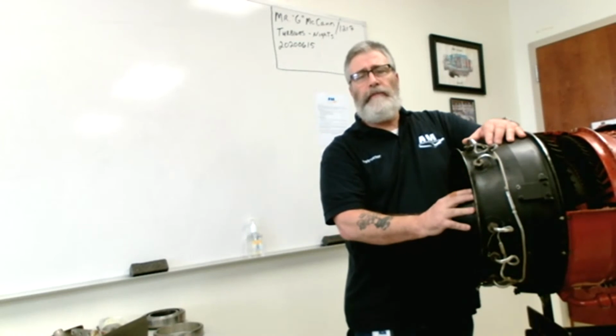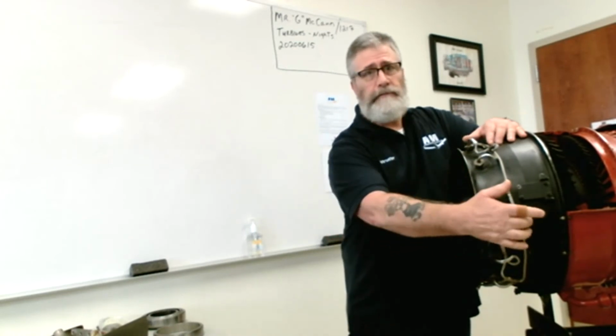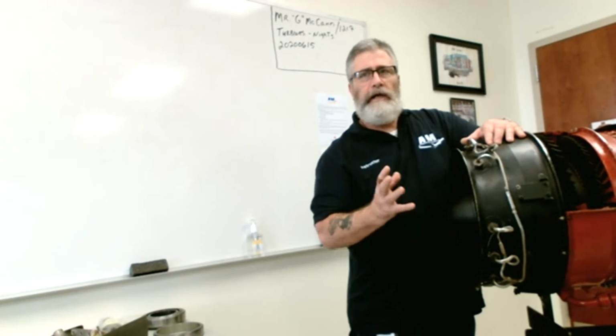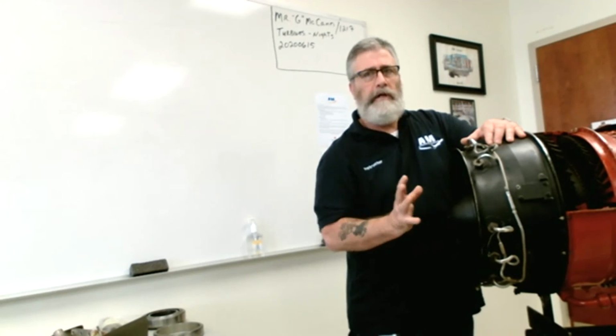The parts that are involved are a fuel source, which is either fuel nozzles or sometimes called a fuel rail. The other thing it needs is a source of ignition. Then there's a thing that goes up inside, which it's better to show you than to talk about, called a flame holder. It's just a big piece of thick metal that goes about halfway up, and that just sets up a little back pressure, right?